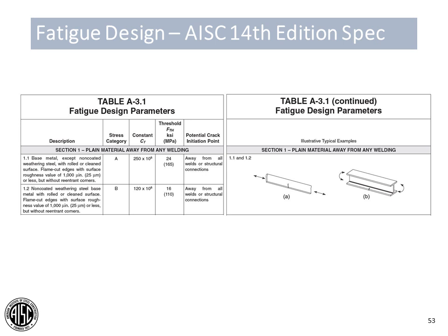This is at Table A 3.1 in Appendix 3 of AISC 360, and you can see there's a relatively long definition of specific locations, the description of the location, and a visual representation of what we're looking at. In this case, we're looking at the interface between the web and the bottom flange of a typical wide flange member.